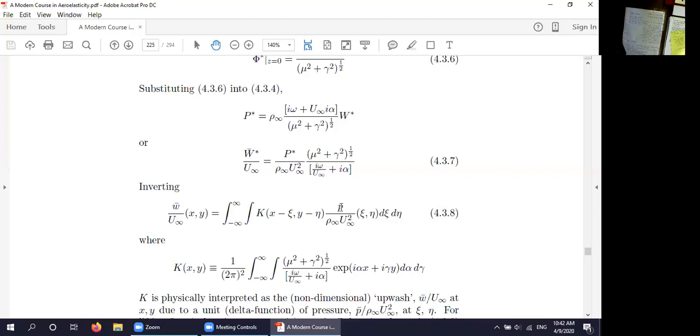But later it was discovered that you can get around all this with a method which is still not entirely rigorously based. It turns out that if you are clever, clever being the following: if I put the points at which the pressure is evaluated in each box at the 1/4 chord, and I put the point in each box where the downwash is evaluated at the 3/4 chord of each box, then the solution tends to satisfy the Kutta condition and all is well.